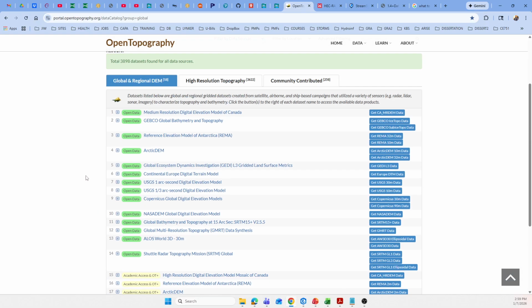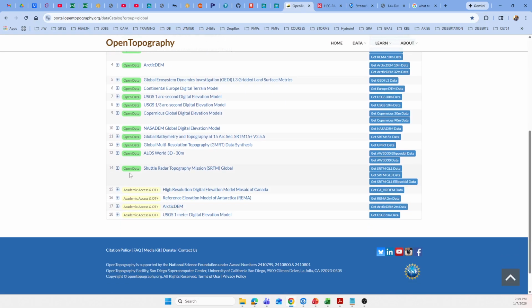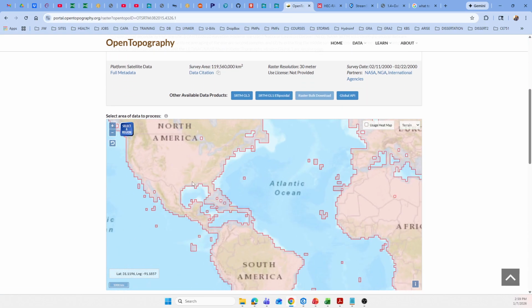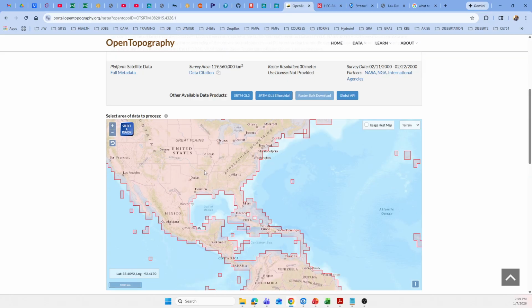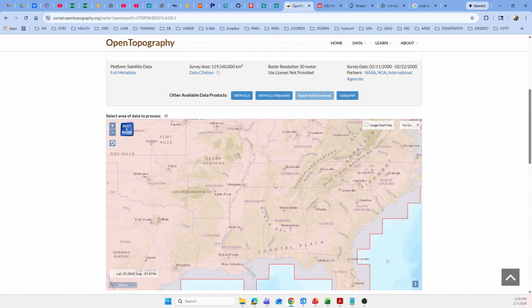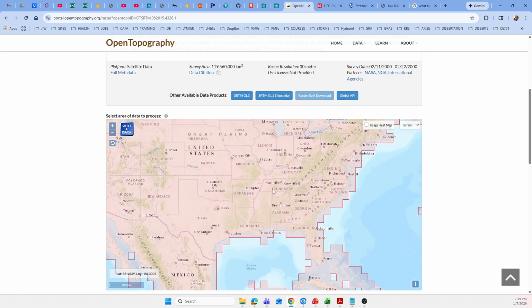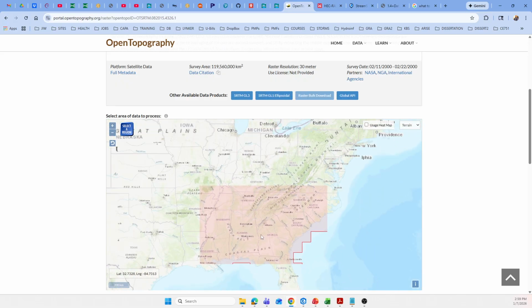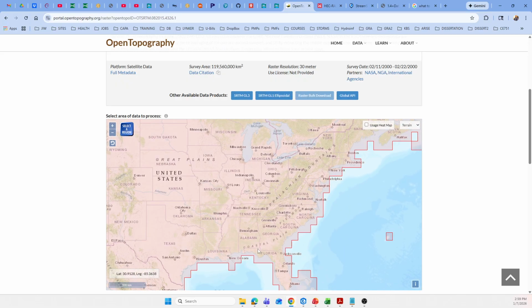To extract the terrain file, as the example is the 30 meters, you need to go in here and click on the GL1 data. When you click on the link, you are going to find your location of interest. I'm looking at somewhere in West Virginia. West Virginia is of interest to me. So I'm going to go to West Virginia pretty quick and draw my area of interest in West Virginia and proceed with this process.